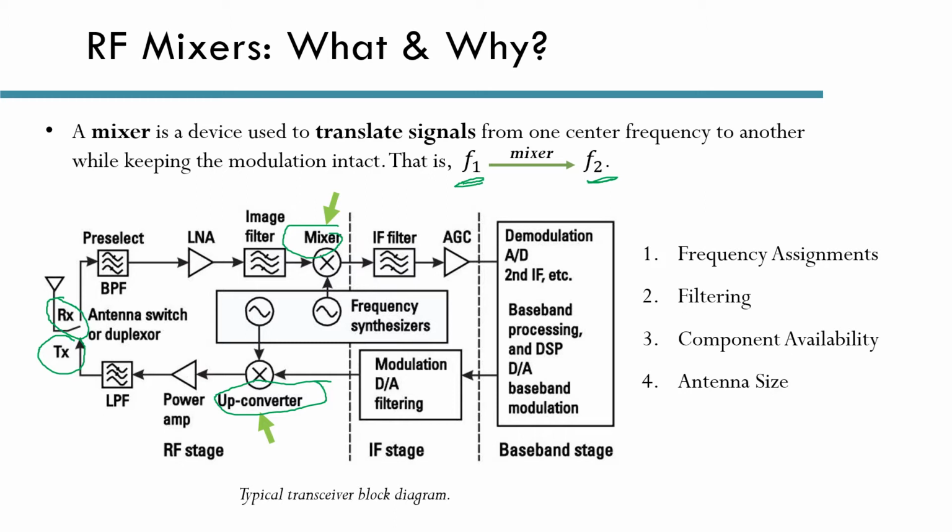amplified and transmitted. And again, why are we doing this shifting in frequencies? Well, for several reasons. The number one reason why we shift frequencies is because the frequency of the signals our wireless transceiver will receive or need to transmit is already chosen for us, already set based on several standards such as Wi-Fi's 2.4 GHz, for example. And these standard frequencies have nothing to do with the requirements of the filters, demodulators, and so on that we will have to design or choose.